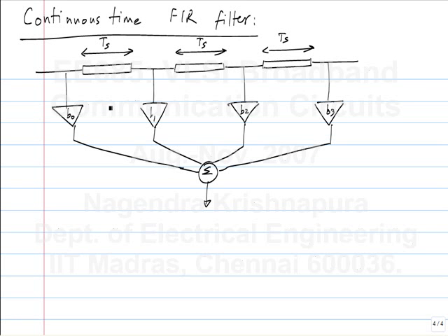In fact, if you implement it like this, you already carried out the exercise for the transmit filter, but like I said, if you have a linear filter, it doesn't matter whether you put it in the transmitter or the receiver. So the coefficients that you calculated in assignment 2 will hold if you put the equalizer in the transmitter or the receiver. Okay. So it will work here. So that's all that's there to it.